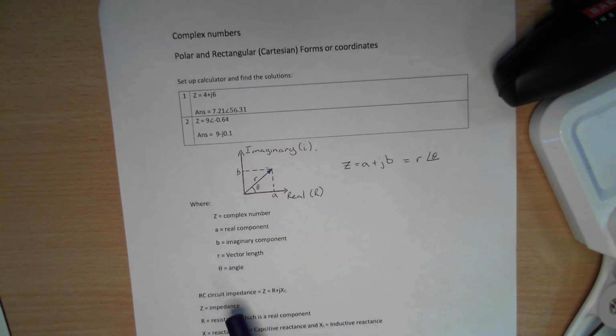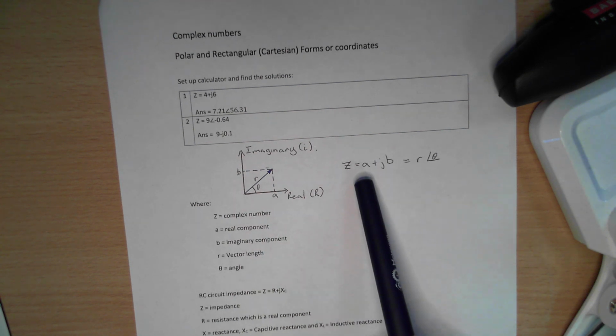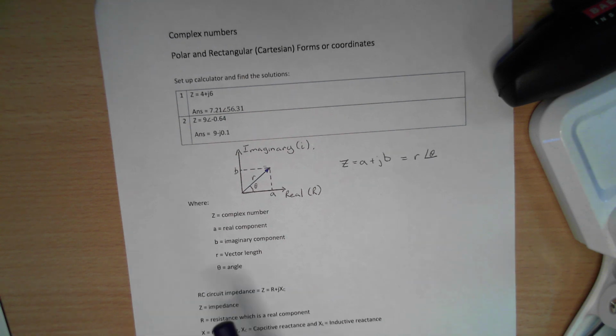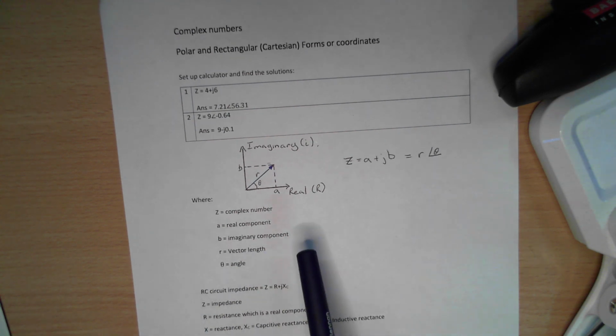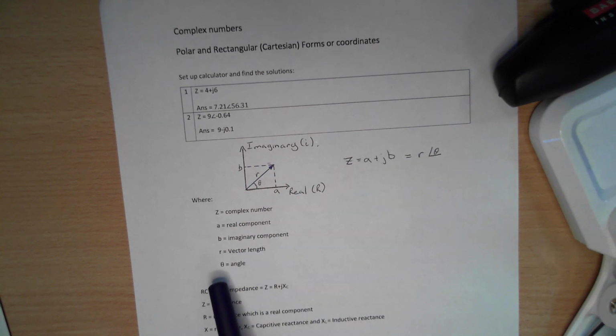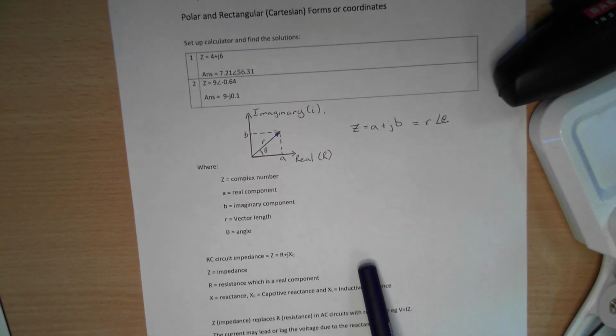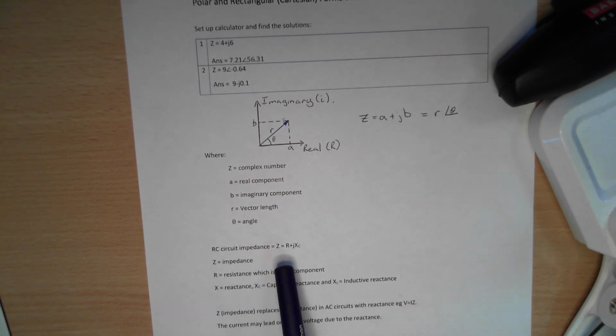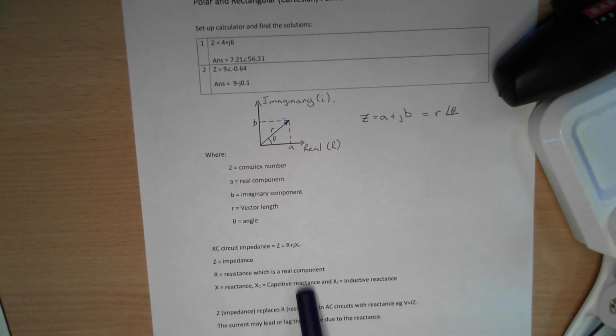So on here, Z is our complex number, a is our real component, like a resistor, and b is our imaginary component, like a reactance that you would get from a capacitor or an inductor. r is our vector length, and theta is our angle. So an RC circuit impedance would be Z equals R plus jXC, where XC is our capacitive reactance, R is our resistance, which is a real component,